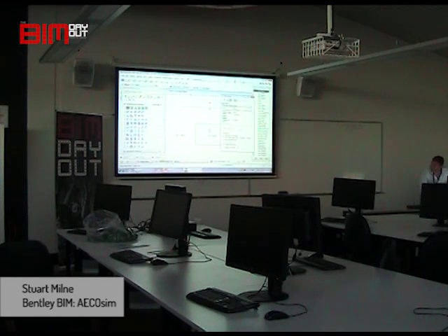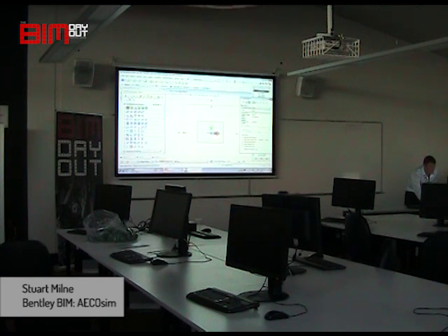Now, at the very top of this dialog box, these buttons are different methods of creating a space. You can draw one. You can use an existing shape to convert it to a space. Or you can do what we call flood a space. So select this one that's got the little paint bucket, flood the space. Make sure your whole object is fitting inside the view. If you need to, you can zoom out, click inside there once and click again to create the space.